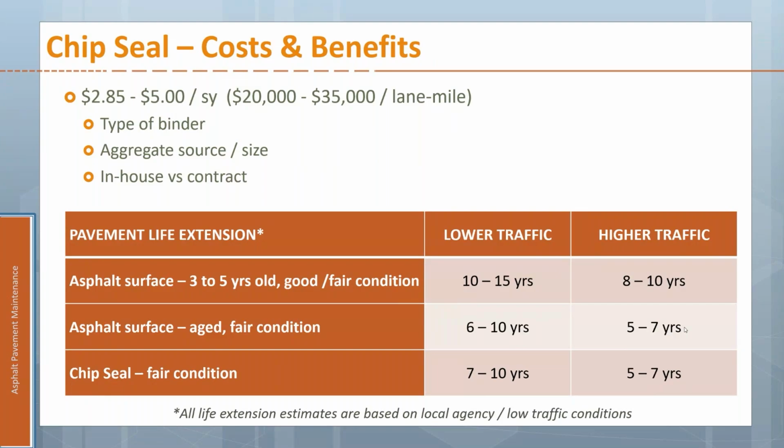Now, for lower traffic, when you put this on a roadway that's already in good to fair condition, you sometimes can get as much as 10 to 15 years. I was on one roadway that they had not done any maintenance on in like 28 years or something. It was unbelievable, but they had done a good job in the beginning, didn't have a lot of traffic, and it just lasted and lasted and lasted.